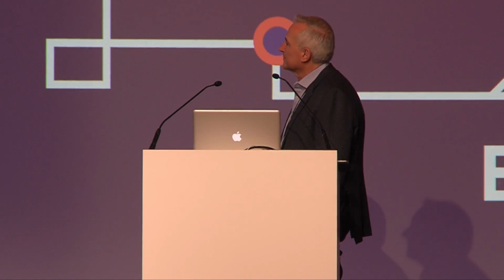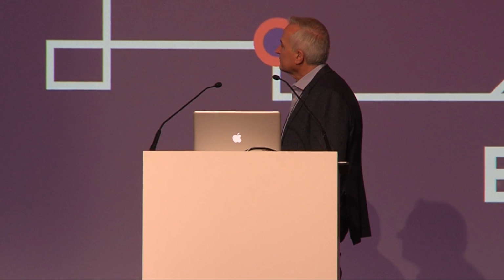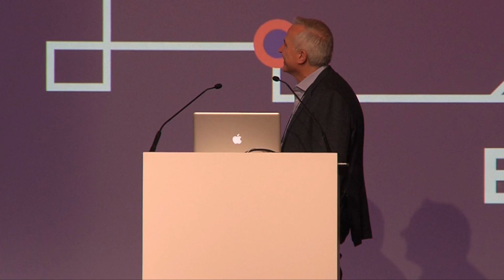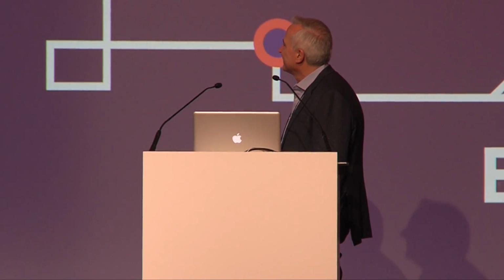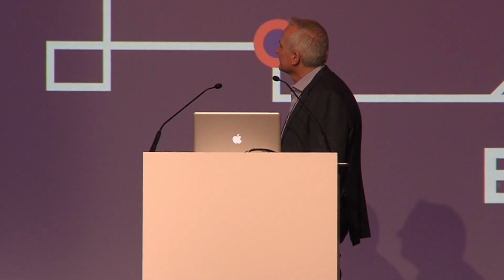Like, we received this drawing. This is an actual drawing we got from users. And I said, look what happens if I do a zoom extents. I do zoom extents, and boom, my drawing disappears. Well, that's an indication. Usually there's an entity at a very high elevation. So let's look at the elevation of these entities. It's a mountain road, so it's not unusual that everything is at 1,200 meters elevation.